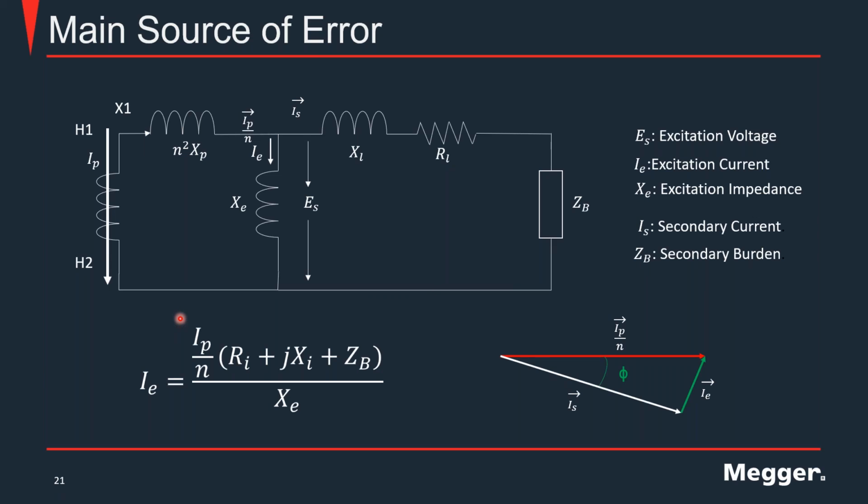As we can see here on this phasor diagram, we have the primary current, then the excitation current, and then the secondary, the actual current that is going to circulate through our load, which is constituted by our meters, our relays, etc. It is going to diverge from the actual image that we want to see of the primary current by as much as the excitation current, and there will also be a phase deviation.